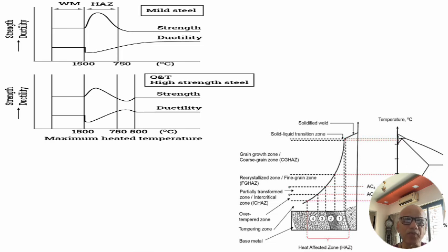When you are welding, you are not only taking care of your weld as it is shown here. The parent metal is already taken care of; we have taken graded, tested material, so this side is not really a worry for a welding engineer, because that's the job of the planners, the procurement agencies and the QC to give us the right material for doing the equipment and joining it. We select a good consumable, so the welding engineer's first job is taken care of, and he selects the right parameters by which we will be able to weld it properly.